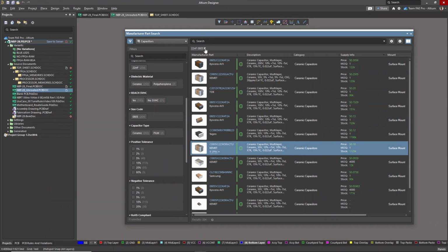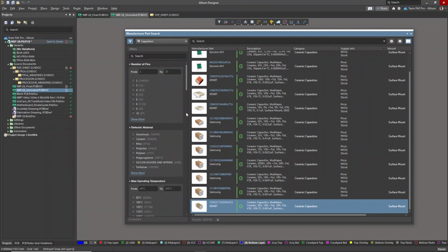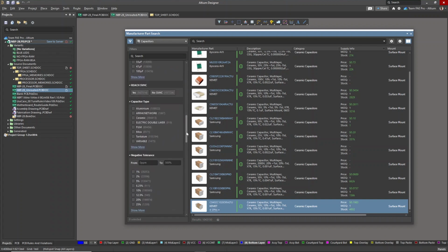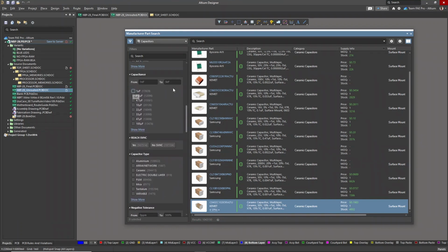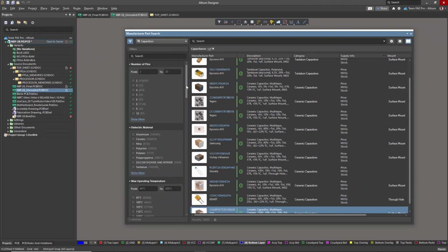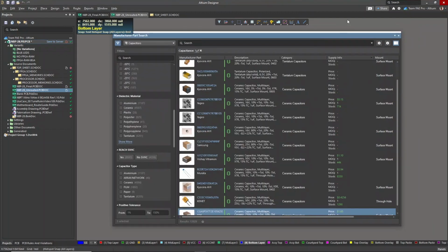I can change this, eliminate what I just typed in, and the whole idea is that this gives you a great environment to even look for values. Say 1 microfarad capacitor. It will update what type of dielectric materials. And it's context sensitive in that when you're checking for a transistor, it's going to bring up HFE and beta and things like that, collector current.